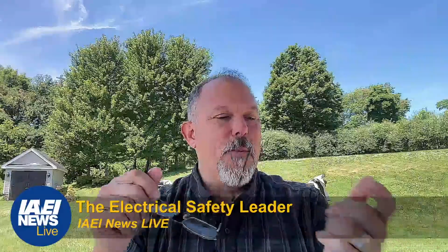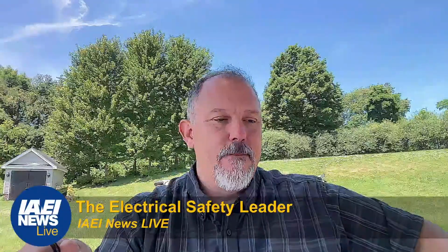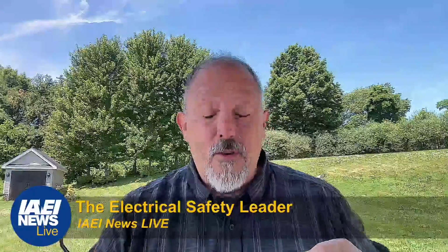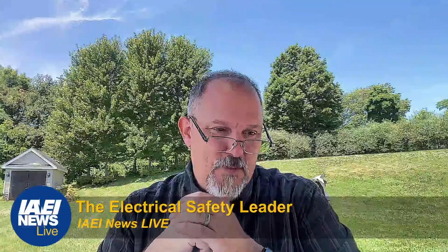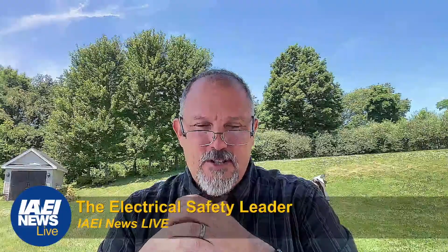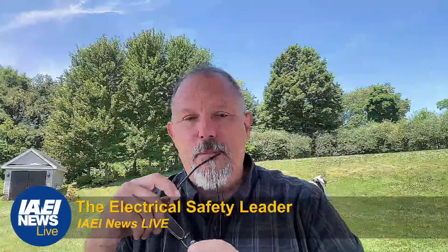So I see your point. What you're saying is that you have to verify absence of voltage before you can actually say it is de-energized, and you can't open the enclosure. So your policies probably could be a little clearer to the electrical worker. Instead of saying that you can't open any boxes that are energized, you could say boxes can be opened after an electrically safe work condition or during the process of establishing an electrically safe work condition, right? So it probably could be written better, to your point.